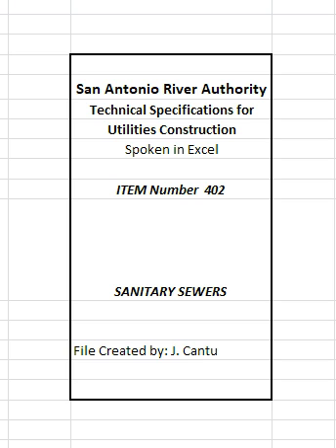D. Pipe stiffness. All mains are to be SDR26 PVC, ASTM D3034, with a minimum stiffness of 115 psi. E. At waterline crossings and where water and sewer mains are parallel and separation distance cannot be achieved as per 30 TAC 217-13, use pressure-rated pipe SDR26 PVC, ASTM D2241, with a minimum pressure rating of 150 psi.